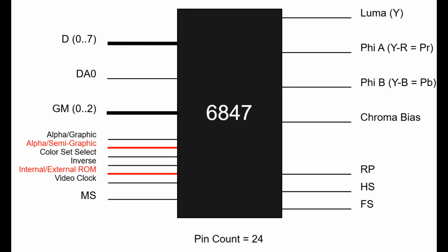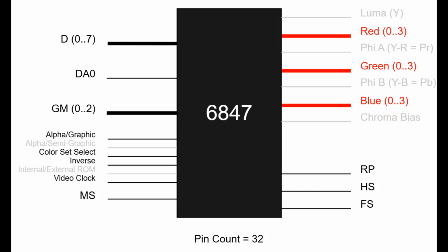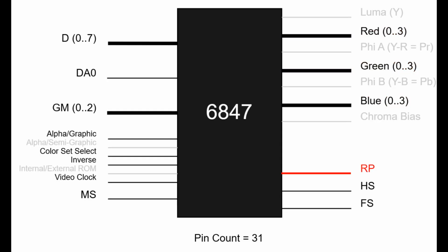The analog output, as previously discussed, is a headache. PLDs don't generally do analog signals. They can through PWM, but that tends to be problematic for video. My solution is just to output digital RGB and deal with digital to analog conversion externally. This decision means I can't just plug my design directly into a socket where the original 6847 VDG lives, or lived. On top of this, there are 2 more outputs for vertical and horizontal sync and a row reset pulse for an external character ROM. I need to keep the sync signals, but I don't need the reset pulse.